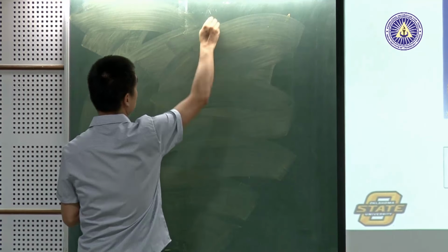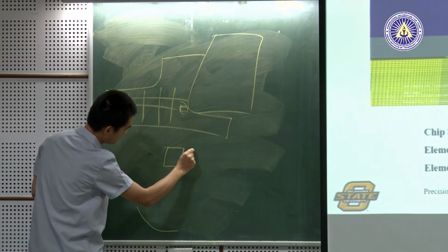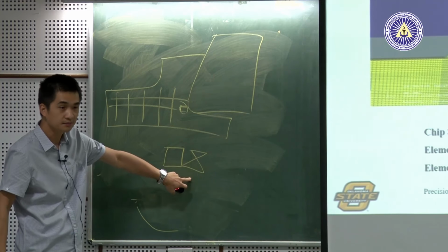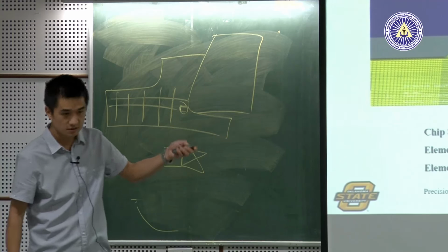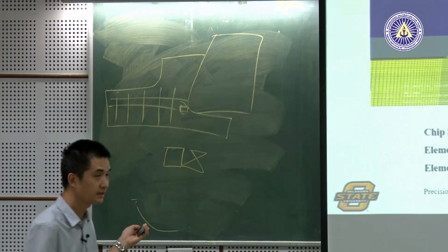In the FE model, especially at this region, the material undergoes very excessive deformation. Originally, let's say we model a rectangular shape, and if this moves to the left and this moves to the right, and it becomes like this, the element is excessively distorted and the simulation stops. It says it has excessive distortion and cannot handle this situation, okay?